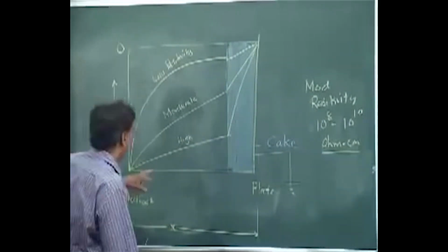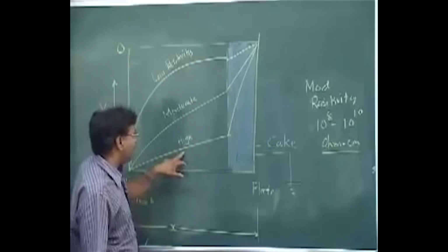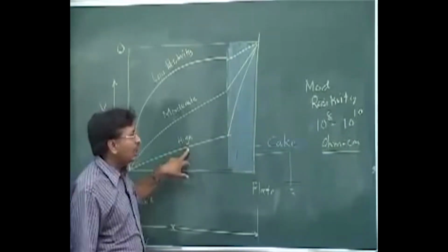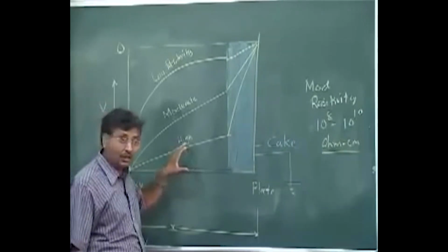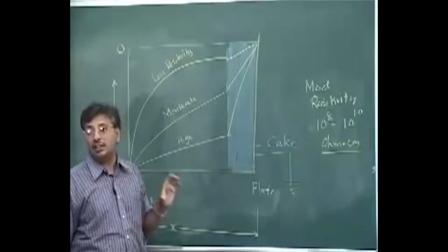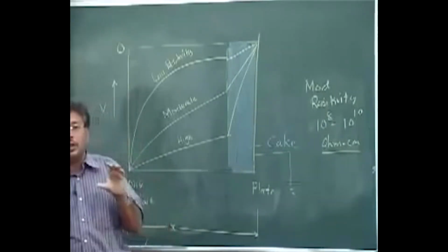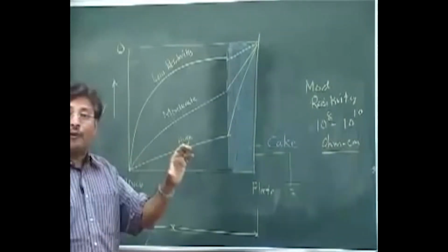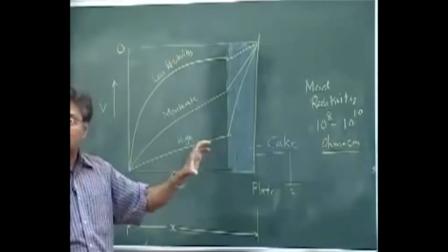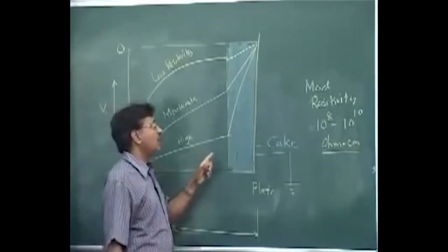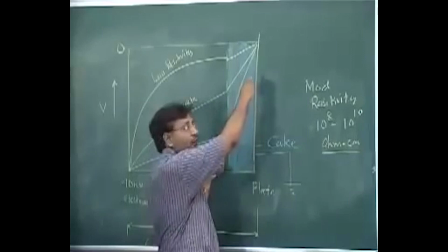Let's talk about the high resistivity. The problem with high resistivity is that, well, one thing is that the particles or the gas may not have enough charge; the electrons may not be able to flow because of the resistivity they are showing. When the electrons are not flowing, they are not likely to hit the particles and they will not be able to go through quickly from the medium and stick to the plate. The larger problem with high resistivity is the voltage difference you see here.